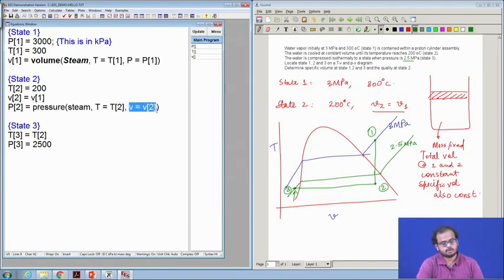I mean, we will see later on that there can be any other quantities, but they need to be two independent quantities. Okay. In the dome, for example, you cannot make use of temperature and pressure to find out other properties, because temperature and pressure are related, they are not independent. Okay. We have already seen this.